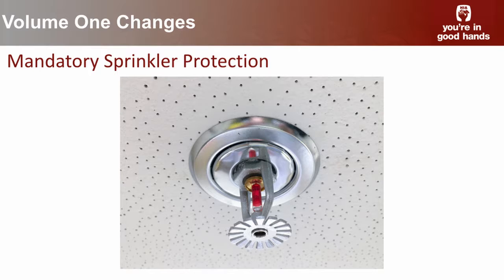So moving into the next change, and as I mentioned at the outset, and Vanessa just put a little bit more comment about this, it was about the mandatory sprinkler protection provisions in the code. These are going to apply to Class 2 and 3 buildings with a rising storey of 4 and above.